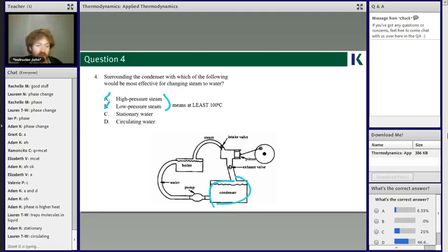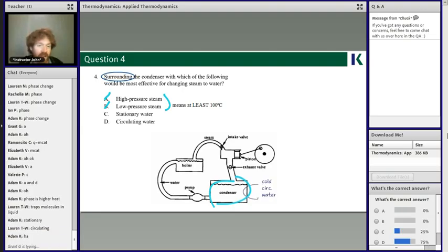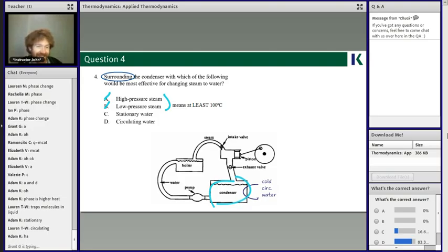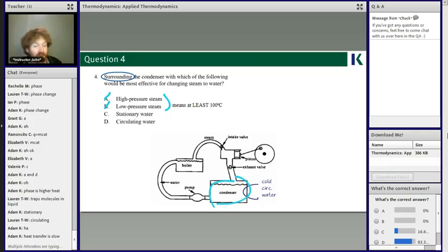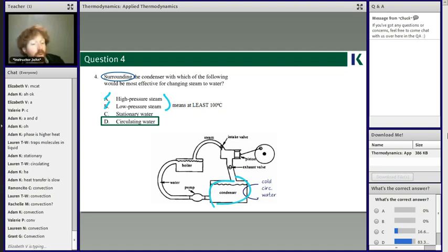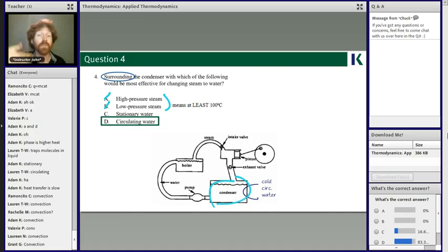And everyone's going circulating. What is the key word on why circulating works best? We talked about this before. It's one of the types of heat transfer. Circulating water means it's using not just conduction, but also convection. Yeah, it's due to convection. It'd be convection cooling. So remember, this is the way convection ovens work: you put a fan in the back of the oven, and if it blows air over the food, it's basically using the bulk movement of hot air to cook it even faster.